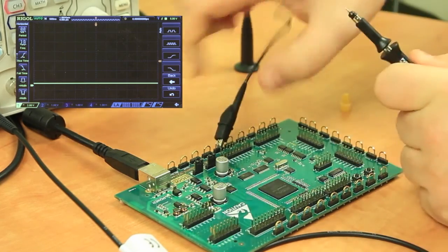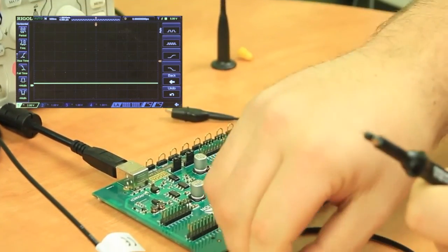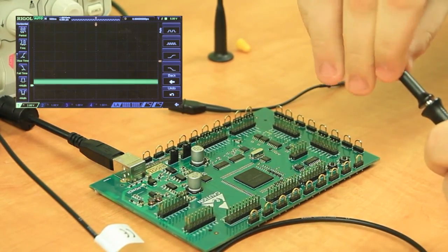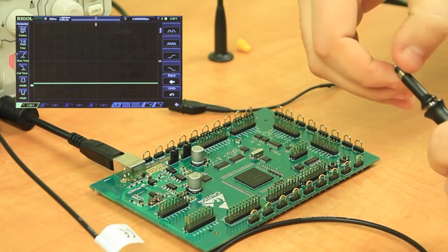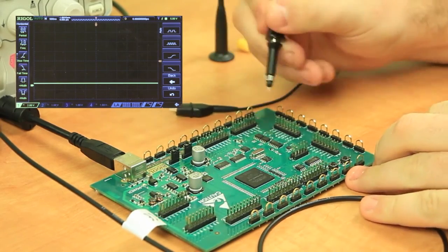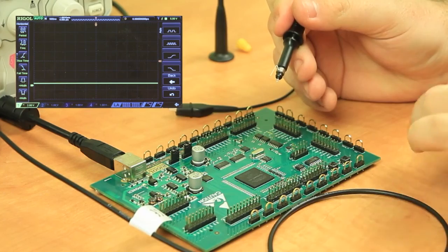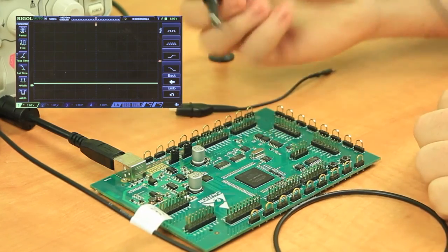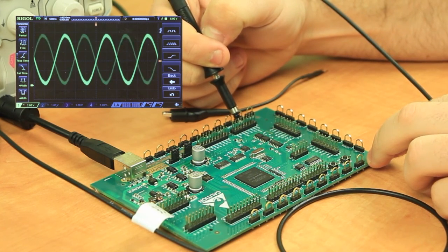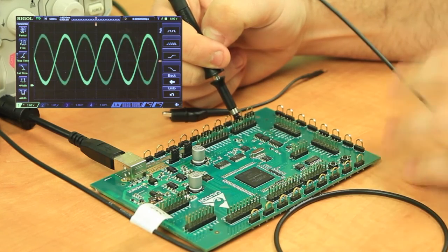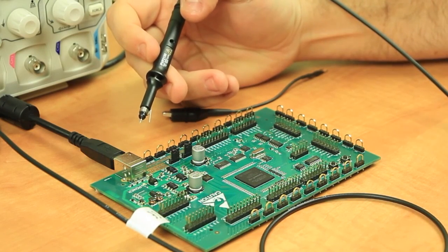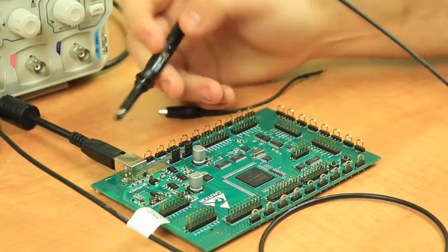Next, I'm going to take the alligator clip off and then put on the grounding spring. This is used more to capture your high frequency signals, and basically signals where you're having potentially some weird high frequency response. With this, the outer spring is connected to the ground and your tip is still the hot end of your circuit. You can use this to capture your signals like so, and you can just probe around for more of your high frequency areas. So that's some of the basics of our probes and how to use them and what they can be used for in different probing techniques.